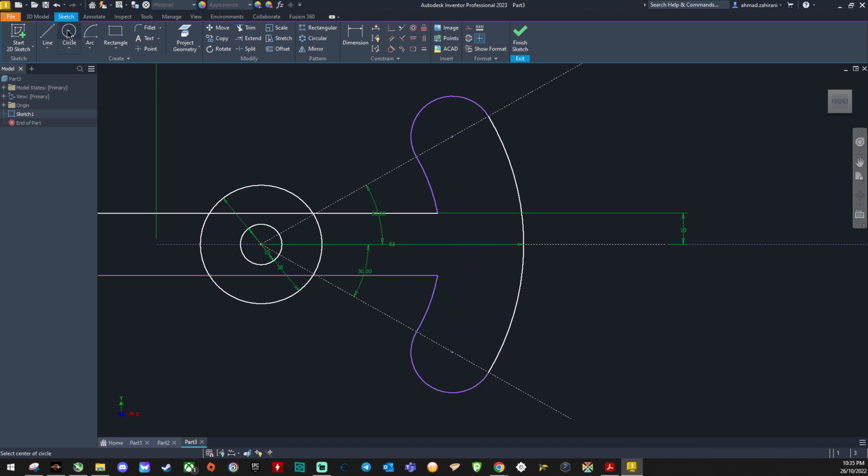So there are another 2 circles that we need to draw. Select the function circle, and then the value here should be 15. Press enter. Below at the bottom the value should be 15, and press enter. Using the function fillet, select fillet, change the value to 5.